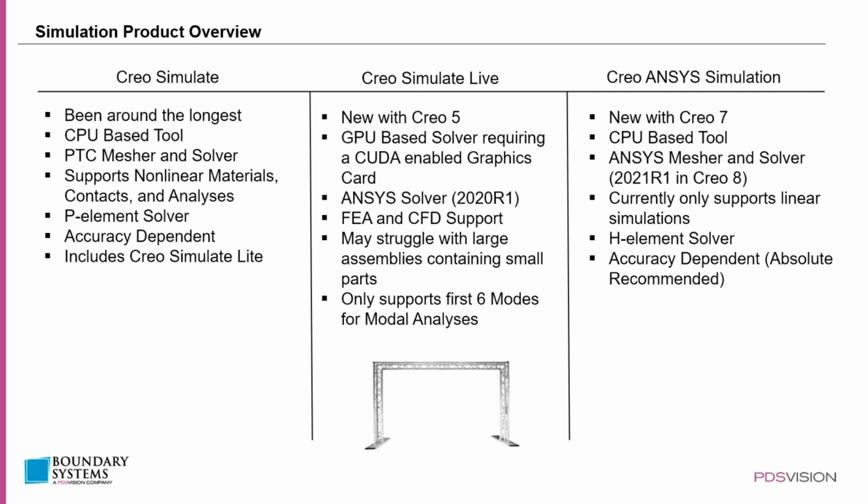It currently only supports linear simulations, so you cannot run any of the nonlinear simulations with nonlinear materials that you can do in Creo Simulate. Additionally, this does not yet support idealizations like shells and beams. So it is a little bit more limited than Creo Simulate in terms of the amount of features that we